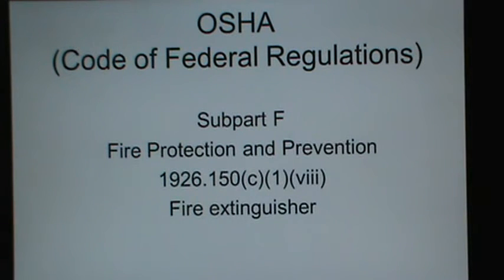Skip a paragraph. This is Roman numeral 8. Portable fire extinguishers shall be inspected periodically and maintained in accordance with the maintenance and use of portable fire extinguishers, NFPA 10A 1970. Sometimes I'll just pull out these little numbers that you would never be able to remember, and you just got to find those.